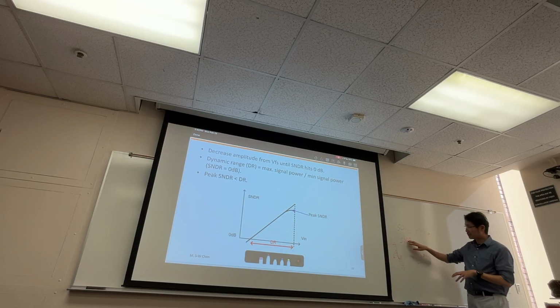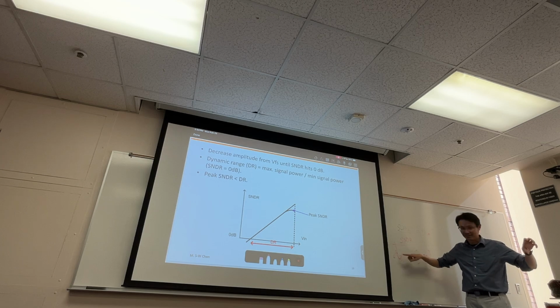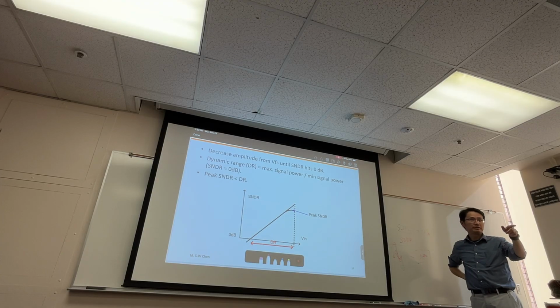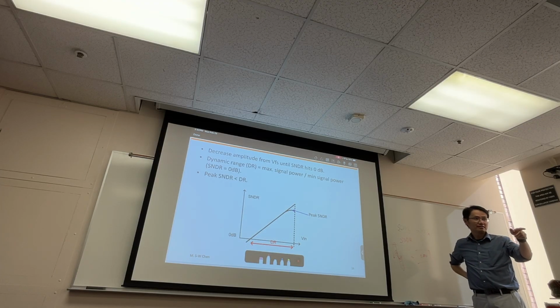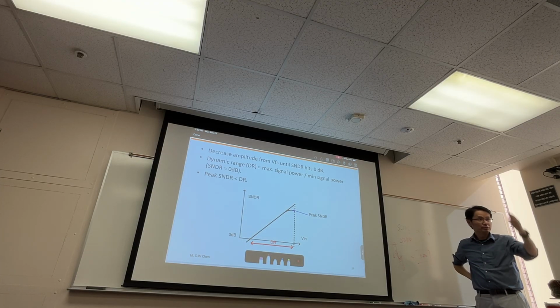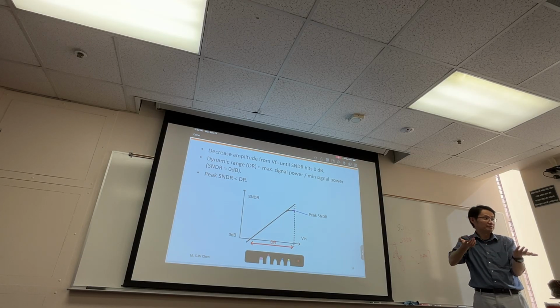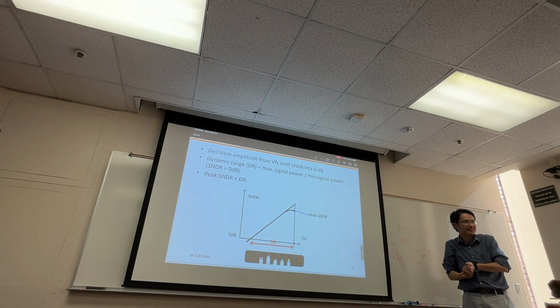Because all this distortion usually scales with your input, right? Your input becomes smaller, usually the distortion is not that bad. Remember 536A? Is it true? You enjoy input, large input versus small input, which one has better THD, right? So yeah, smaller the better, right? Usually with smaller input, your circuit will be more linear.